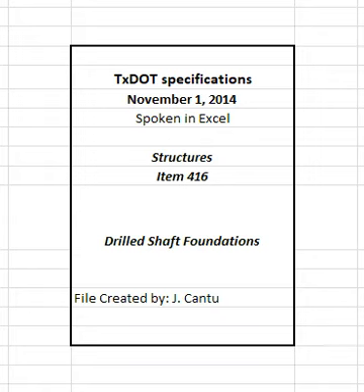In this case, all of the provisions of Table 3 must be met except that the maximum specific gravity is not to exceed 1.12. Sample slurry from the bottom of the hole, before placing concrete, and test it in accordance with TEX 130E. Use a pump or air lift to remove slurry that does not meet the requirements of Table 3 while adding fresh clean slurry to the top of the hole to maintain the slurry level. Continue this operation until the slurry sampled from the bottom of the hole meets the requirements.